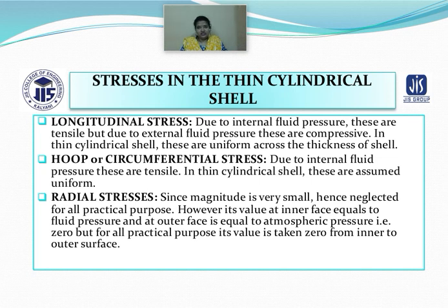When the vessels are empty, they are subjected to some internal pressure as well as external atmospheric pressure. In that case, the resultant is always 0. But when it is filled with compressed air or some gas or fluid, it feels internal pressure, and this pressure helps to develop a tensile stress in the wall of the cylinder. Why? Because the thickness of the cylinder is much less than the diameter of that particular shell.